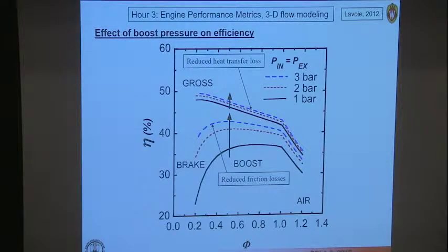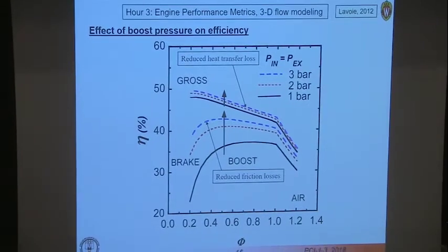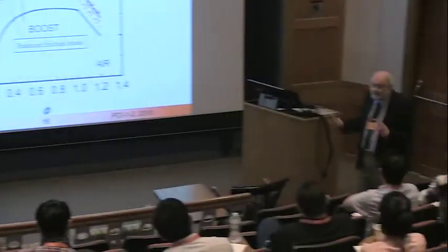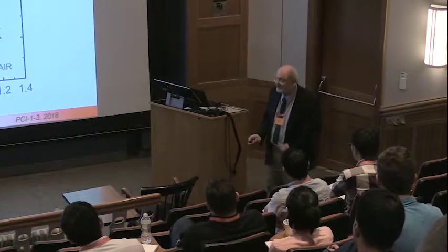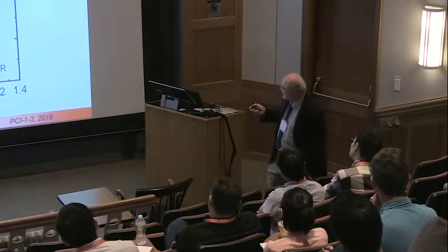Okay, boost pressure. So remember that I mentioned earlier that in 1925, the turbocharger was invented, and this really shows what a great device that is, because by boosting the intake, you can reduce friction losses significantly. And why is that? Well, you're essentially sending high-pressure air into the combustion chamber, which pushes the piston down against atmospheric air in the crankcase. So you're getting some free work out of this system. Free, right? But you're getting some work out of the system, which effectively reduces friction.